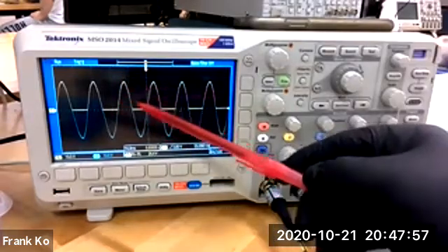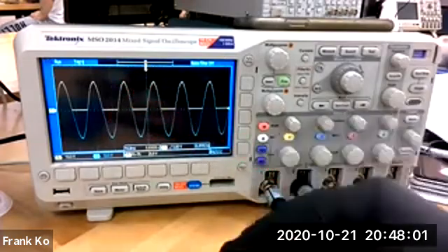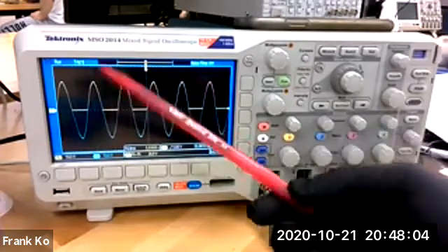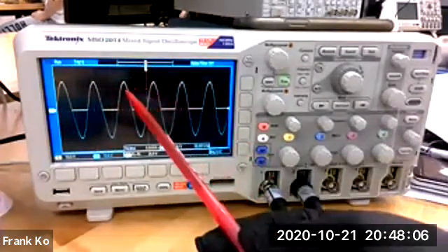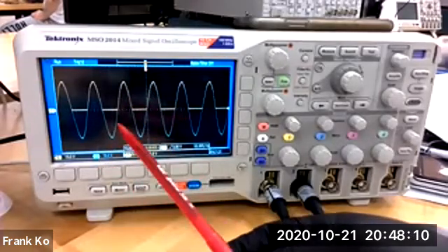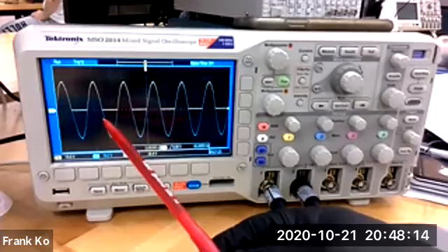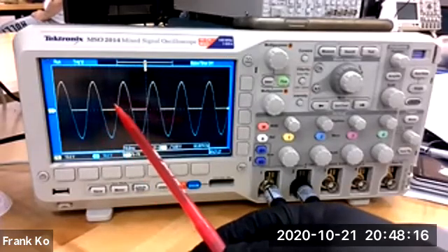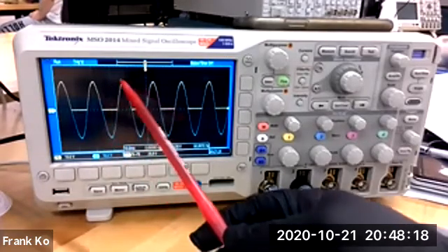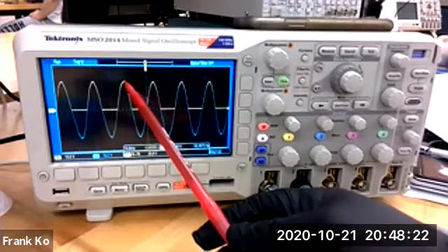Okay, it looks like we're not getting any loss of voltage from one to the other. In actuality, the output is a little bit less than the input because our peak is happening, in my particular case, somewhere around a 26 volt peak. The output is going to be a little bit less.